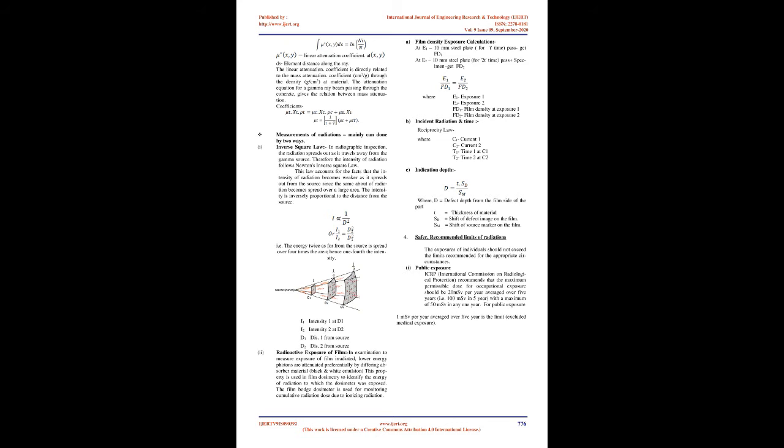2. Admixtures. Superplasticizers are beneficial in reducing water to minimize bleeding and maintain a cohesive mix that has minimum segregation. Water reducing admixtures will increase concrete density by reducing the amount of water. Water is the material used in HDC with the lowest density. Shrinkage reducing admixtures ensure dense, crack-free concrete used for radiation shielding concrete. One of the widely used superplasticizers has a Na2O of about 5% and is added at 1% of cement weight to the concrete. Lithium-based compounds can be used with lead shot to control the alkali reactivity.